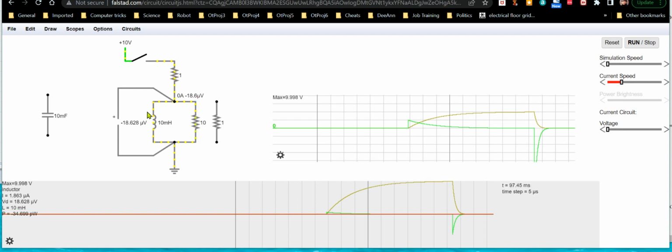But again, also you'll have trouble with your inductor. You have to make sure your inductor is going to handle like 10,000 volts, okay? Because there's a good chance you'll have arcs between its windings, and that'll damage or destroy the inductor. Not to mention, there is such a thing as capacitance between the windings of an inductor too. That may be a problem there a little bit.